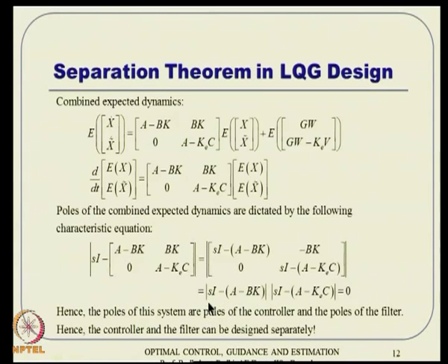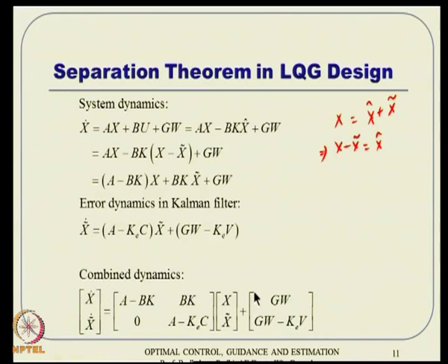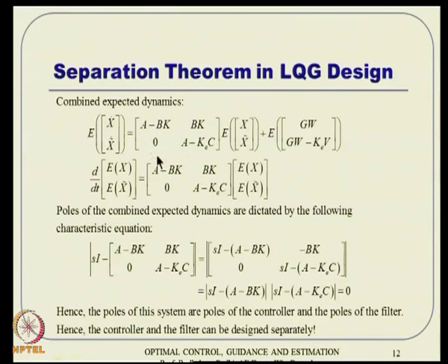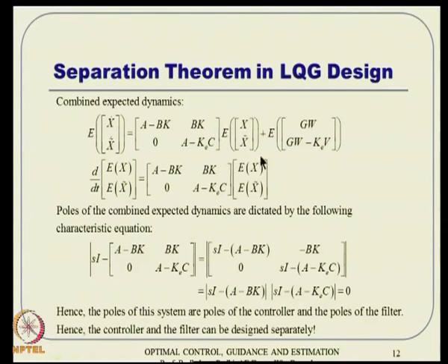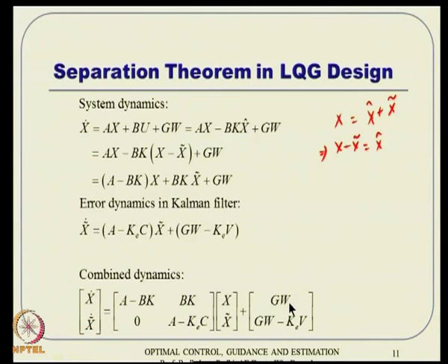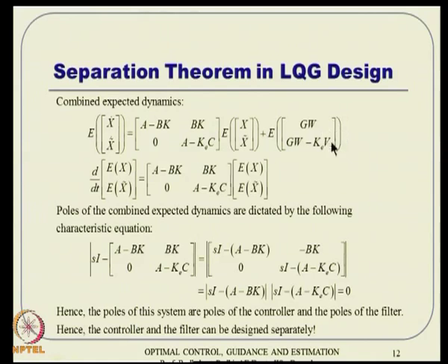So, x dot and x tilde dot is this here, and this part operates like that. If you see the expected value of the error dynamics now, because everything happens, these are all random white noise and all that, remember that. So, we can't talk about this dynamics per se, but remember these are zero mean white noise. If you take expected value, it comes directly here, because this is a constant matrix. Remember these are time invariant linear systems, LTI systems. So, expected value will come directly here, because it is a linear operator. You take expected value of that, this matrix times expected value of that, plus the expected value of this quantity. But this is essentially zero mean white noise, both W and V. So, the expected value goes here, and all these things will be 0. So, this is as if it is not there actually.